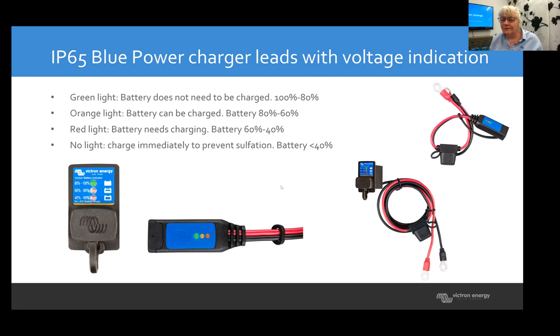The sort of resting voltage of a battery is about 12.6 volts. So that's if you measure a battery, that's more or less always what you measure until the battery is almost empty, and then you start seeing it drop.